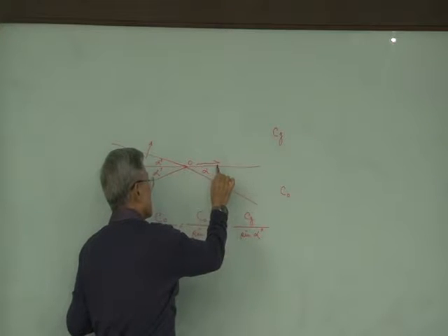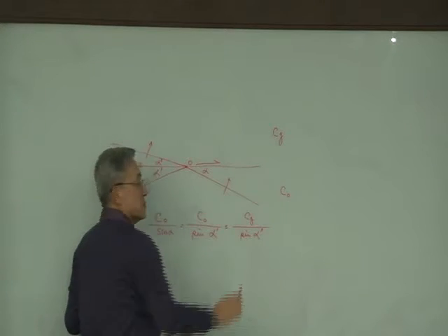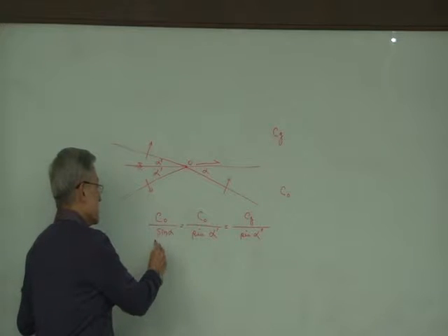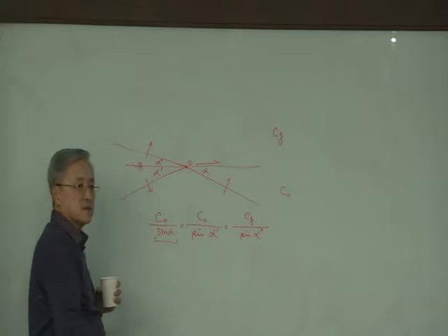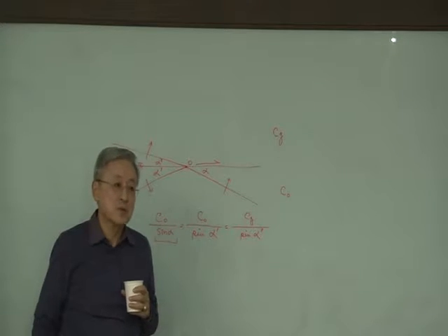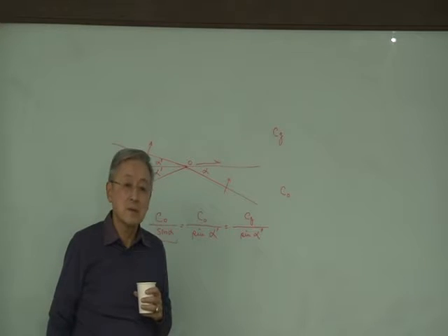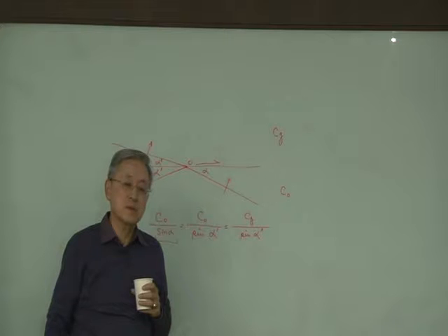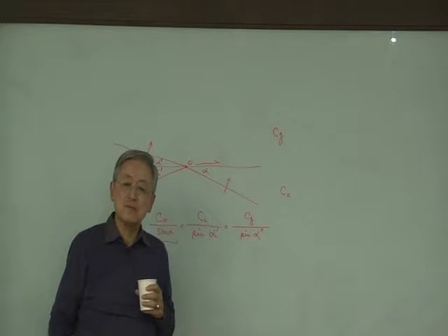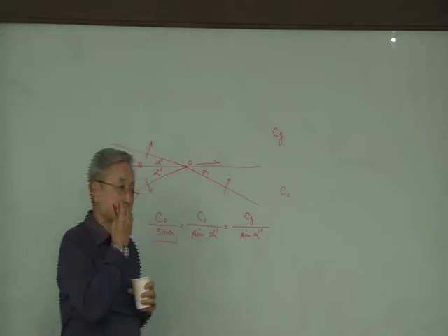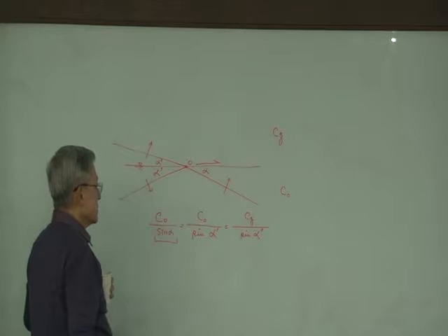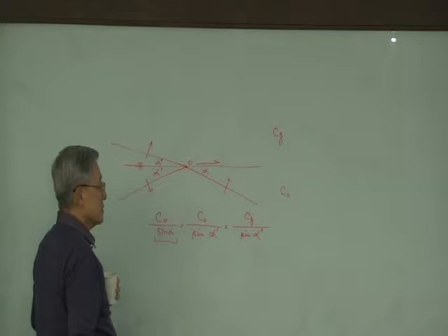If you compute the acoustic velocity along the surface, that's what this is. And C naught over sine alpha is larger than C naught, because the maximum of sine alpha is 1, otherwise it's below 1, which means C naught over sine alpha is higher than C naught, right? So this is one thing, Snell's law.